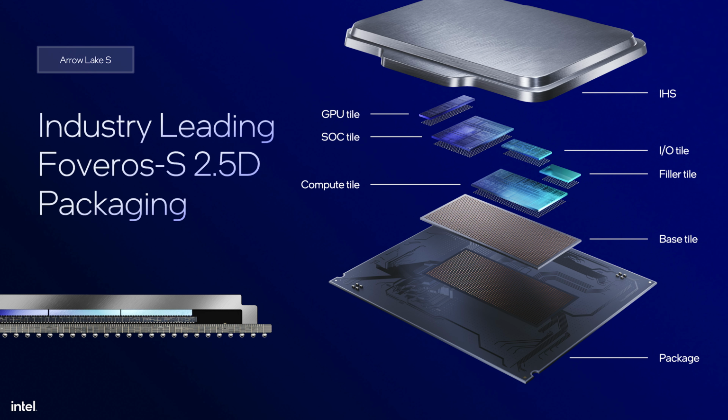And the interposer can be active, meaning that there are transistors and active components on the bottom, and that's considered 3D, or it can just be passive, and you can use it as a very fast conduit for all the chiplets on the top to talk to each other. So we do 2.5D, which is a passive interposer, and we do 3D, which is an active interposer.